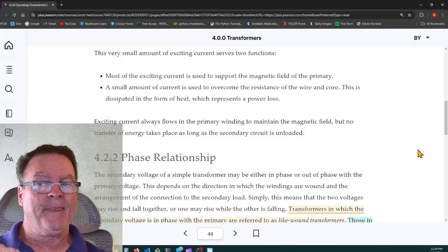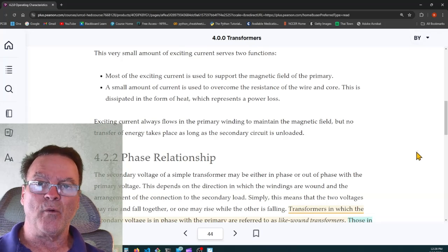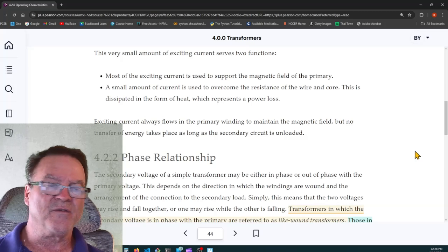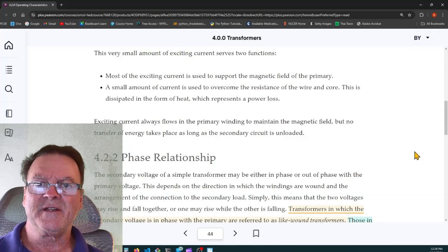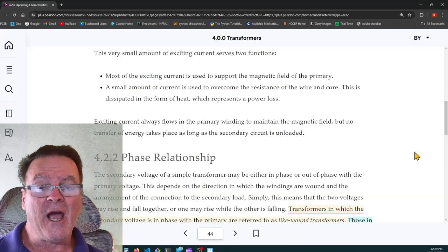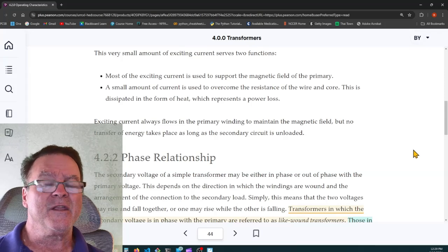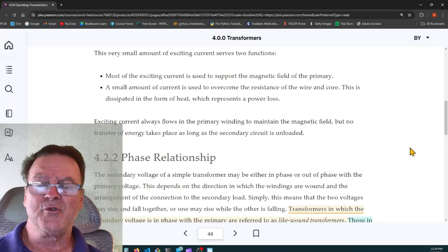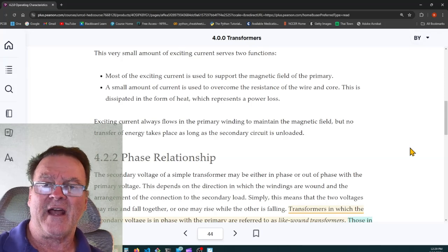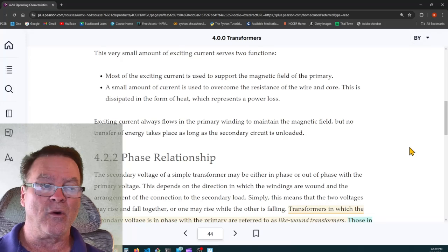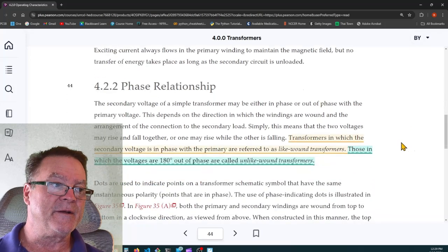So I'm going to say it, there's no such thing as a 100% efficient transformer. They've gotten close. If you have a 2% impedance and a 98% efficient transformer, that's a pretty good transformer. If you have a 99% efficient transformer, you've paid a lot of money for it. Instead, what they usually do is just oversize the transformer by 20%, and they get the power that they need out of it. You don't have to have a 99% or a 100% power efficiency.